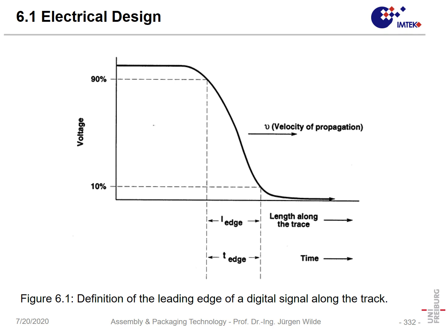But there is a leading edge of that signal. Typically, the leading edge is measured between 10% of signal rise and 90% of signal rise. Also, such tolerances determine the switching points of electronics. And so that initial length is the so-called edge length of that signal.